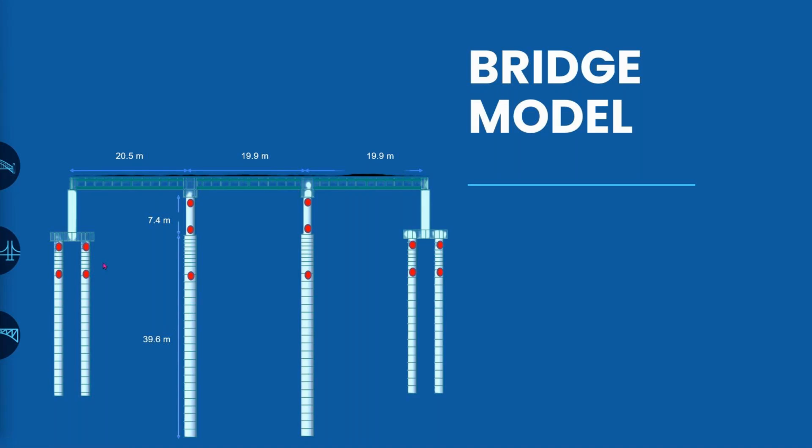Now, the problem that we generally face here is how to find the point of fixity for this particular structure. Most engineers assign the plastic hinge throughout the length of the piles, so that depending upon the highest moment that we are getting at one particular point, the plastic hinge could form at that point. So one method is to assign the plastic hinge throughout. The second method is, depending upon the approximate formulas that we have to identify the point of fixity in the pile, we can specify the plastic hinge at that location.